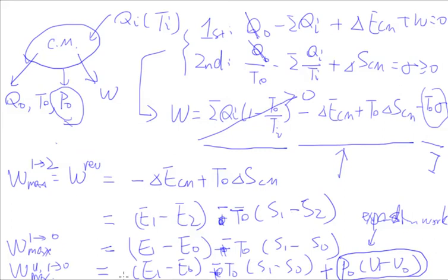We can define this quantity as the exergy of a control mass, and we denote that as phi. We can also express that in mass-specific form, which is m times little phi. So that's exergy for a control mass, and that measures the ability to do useful work.